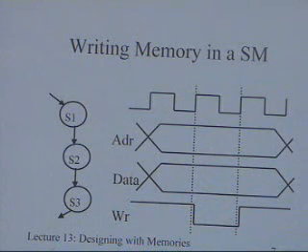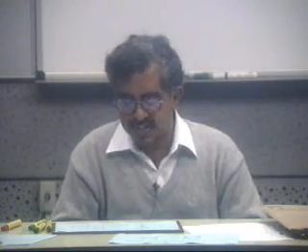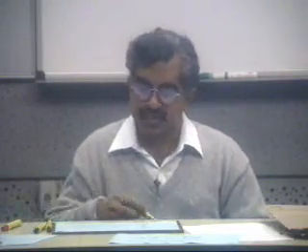Because now what's happening is if you use the same state machine, after all when you are using a RAM you are also going to perform read sometime and write sometime, and each time you are performing a read you are using 1 clock cycle, and each time you are performing a write you are using 3 clock cycles. Obviously you are not using all the capacity of the design. So typically designs are done with some more effort, but let's say if you really want to do a safe design and you are not really concerned about the speed of your design, then you can use this. Later on we will see how variations to this can be done.